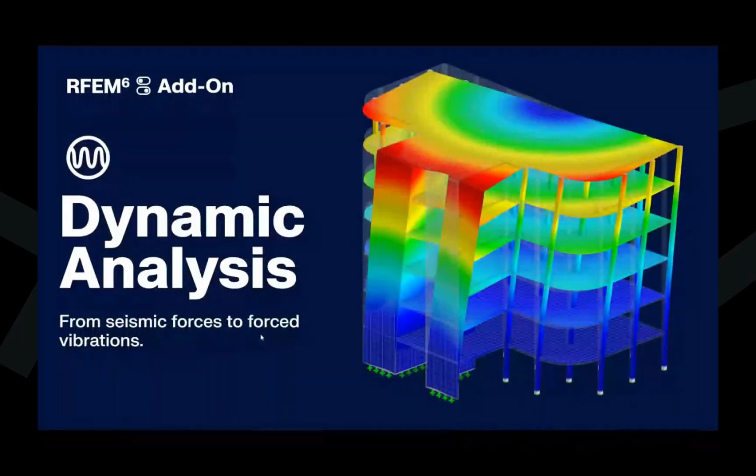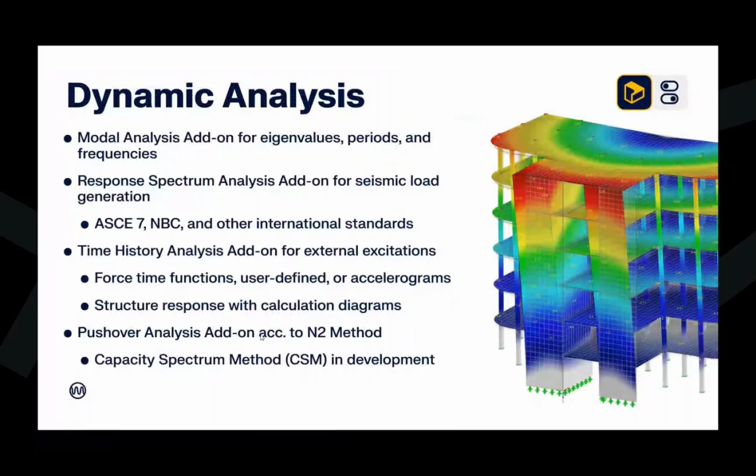Moving on to dynamic analysis. So we have several different add-ons depending on the dynamic analysis needs. So everything from seismic forces to forced vibrations. So we begin with our first add-on, the modal analysis. And this will take our structure and carry out this eigenvalue analysis to determine the natural periods, frequencies, mode shapes, accelerations. This add-on is always a prerequisite before we can utilize any of the other dynamic add-ons listed here.